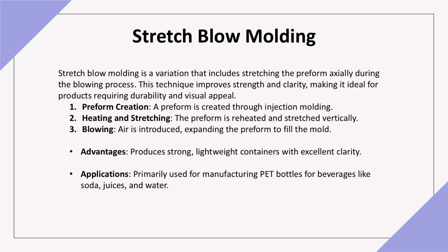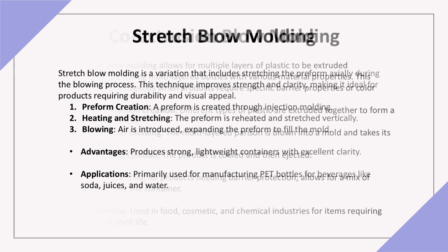Stretch blow molding combines stretching with blowing for strength and clarity. Preform creation. The preform is injection molded. Heating and stretching. The preform is reheated and stretched. Blowing. Air expands the preform to fill the mold. This technique produces strong, lightweight containers, ideal for beverage bottles.